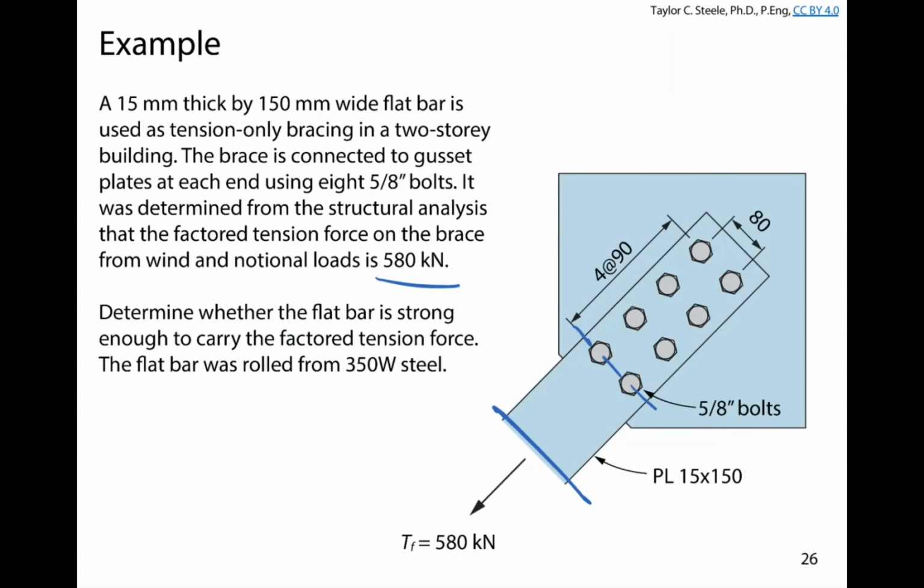There's not too much steel in there. It's threading the needle, so to speak. We have 587 kilonewtons of capacity versus the 580 that we need. Our TR is 587 kilonewtons, which is greater than TF, which is 580. So this is an acceptable design for this connection.